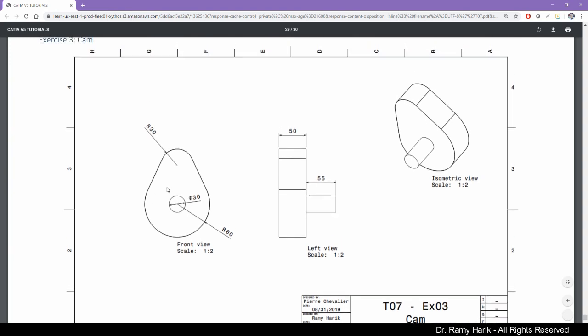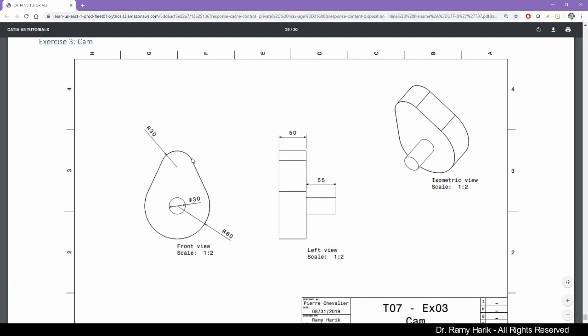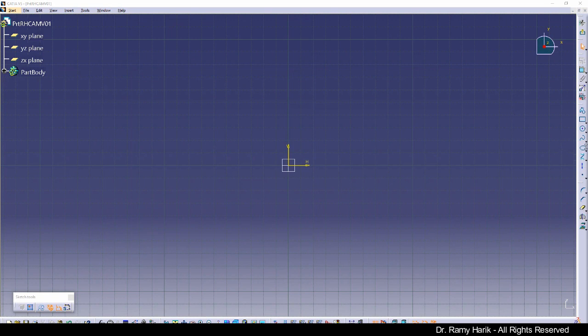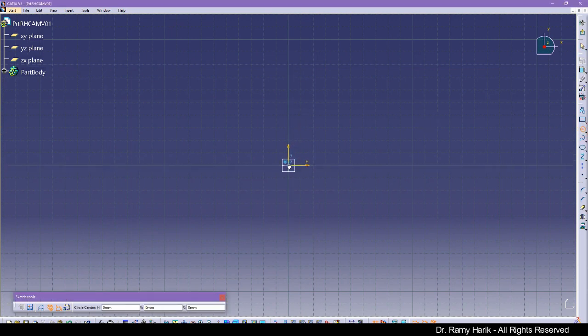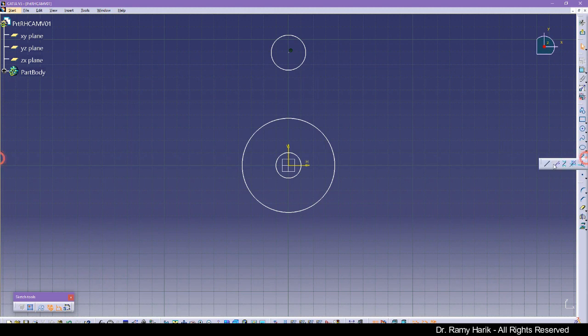We're going to create a circle, create another circle, a third circle, create bitangent lines, and put all the dimensions. Let's go ahead and do it. So I'm going to double click so that I can create several circles at the same time, and then a third one in here. Then I am going to create, so this is the icon underline, you have a bitangent line. So I'm going to select these circles and create those bitangent lines. Next thing is I'm going to put the dimensions. So the dimension of this one, dimension of this one, and finally the 70 from here to here.